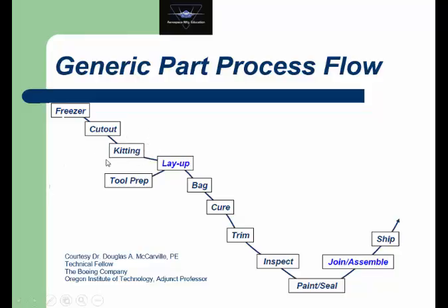So you have the instructions, you have any resin that you might need, you have all of the cut out sections of the prepreg material, tape, vacuum bag material, everything that you need is in this kit. So you have it all in one place, and you roll this over to the mold, and then the operator uses that kit to build up the part. Obviously, if you have pieces left over when you finish building up the mold, you have a problem, and you probably want to stop before you put any extra cost into this part.